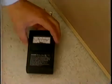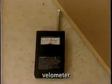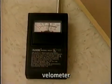Or a velometer can be used. This is an instrument that measures the speed of the air going in under the door. And finally, there's the amount by which exhaust exceeds supply. This is called the offset and is expressed either directly in excess CFM or else as a percentage. For example, you could say that a room is 10% negative. This means that the exhaust air quantity is 110% of the supply.